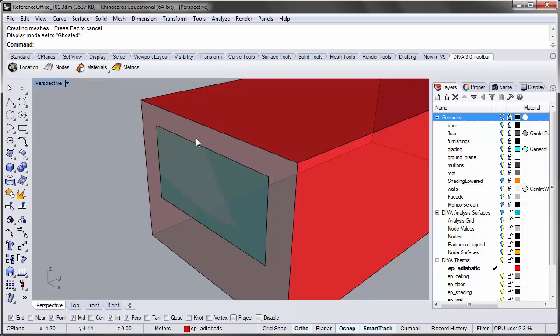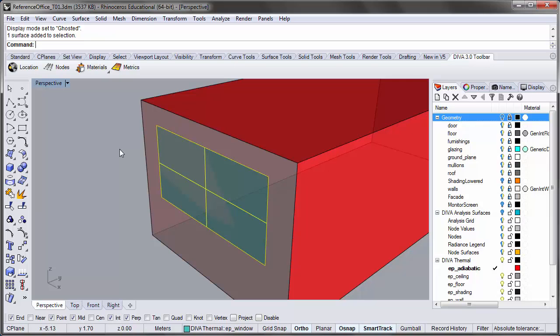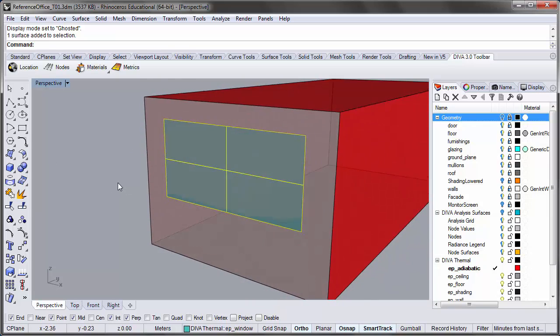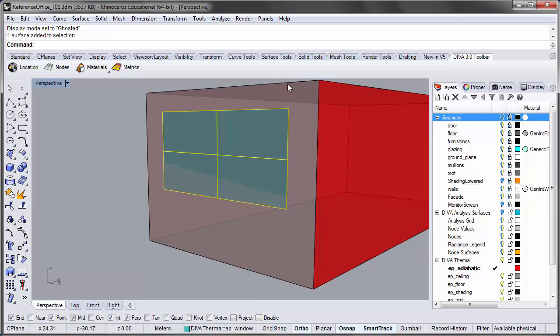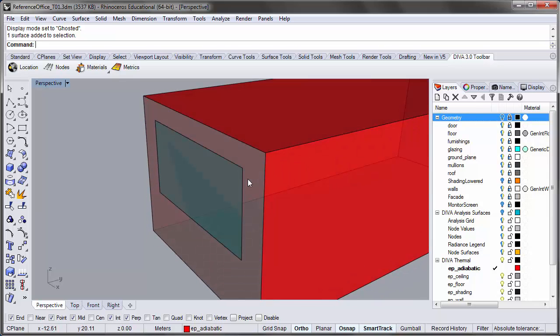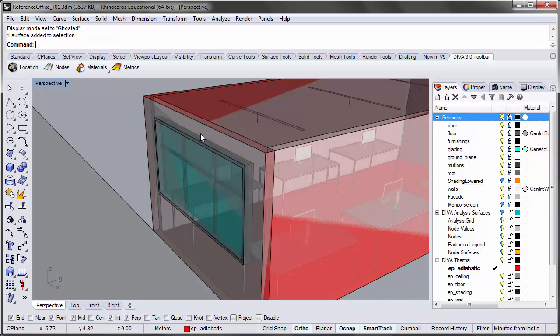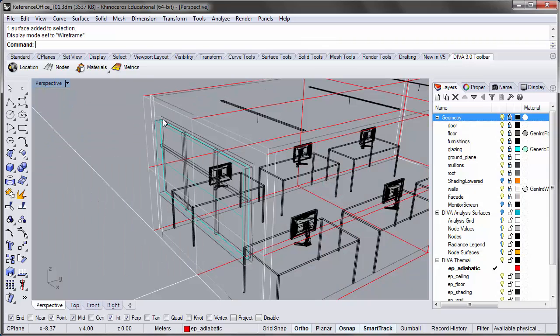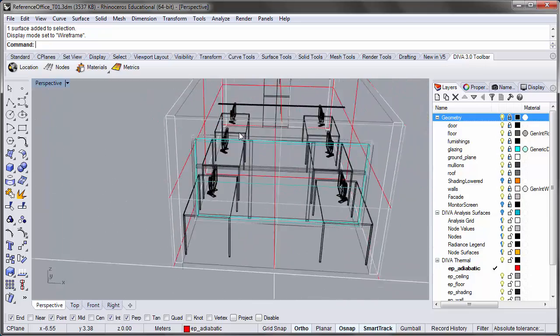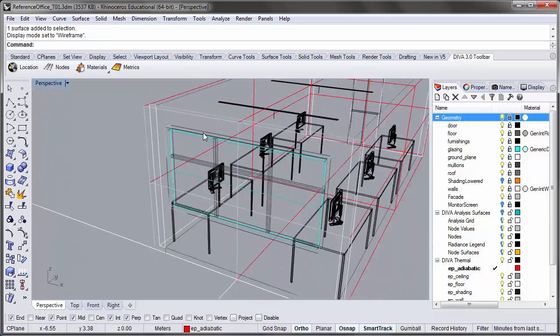It's also important, when creating a thermal model, that those windows don't touch the edges of the walls that host them. Here we have a window that's inset a little bit, with some wall around it on all four sides, and that's critical in order to avoid any kind of complications in our energy model. And if I turn my thermal geometry back on, you saw that the glazing for the daylight model is on the inside of the wall, and my geometry for my thermal model is actually matching the outside plane, the outside edges of my exterior wall.